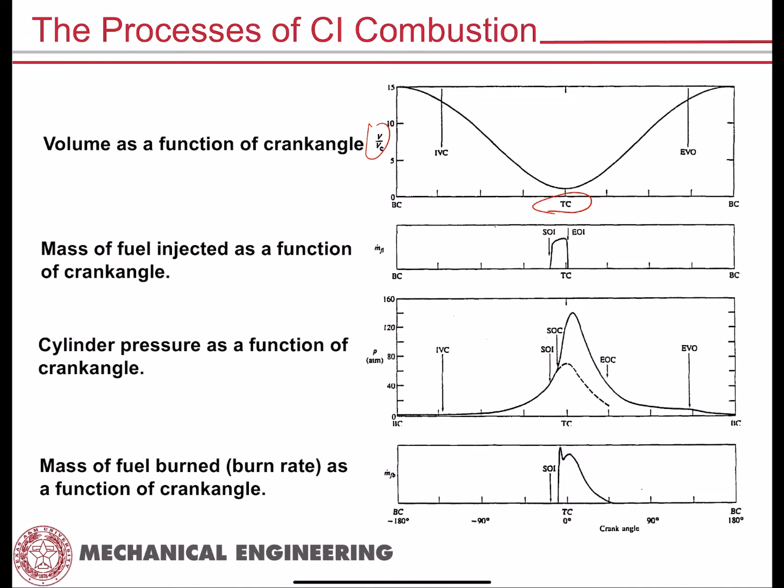But of course, the piston starts at its bottommost position, maximum volume, moves upwards, so the volume decreases until it reaches a minimum volume at top dead center. And because of the kinematics, it reverses its direction and starts to expand the volume. Then eventually the piston reaches bottom dead center again. Now, just to create a frame of reference, this is the compression process, this is top dead center, and then this is the expansion process. So combustion is going to start somewhere around here, when the piston is at top dead center.